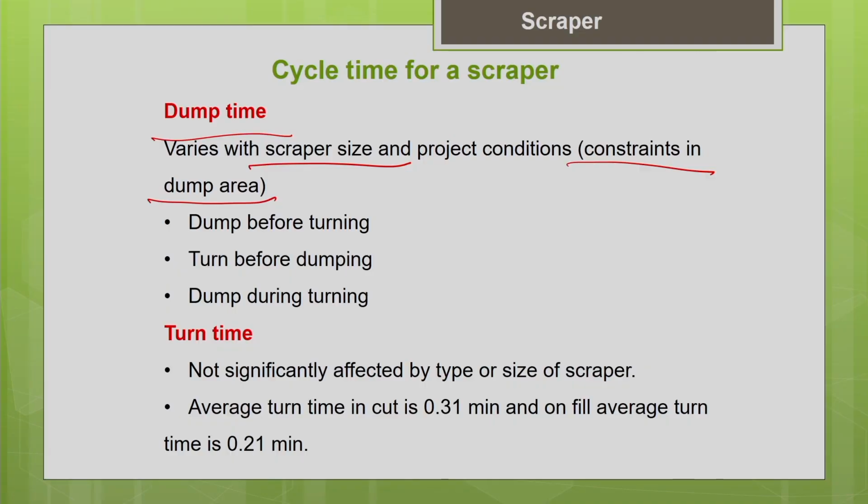That is why very commonly you can see that if the terrain is going to be very hard, very tough consolidated clay, then in order to enhance the productivity of the scraper, they initially use a bulldozer with a ripper and rip the soil. They loosen the earth so that you can easily use a scraper for the loading operation. That way you help the scraper to reduce the loading time.